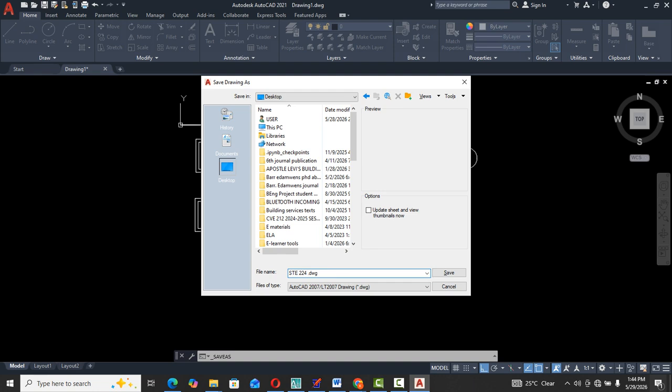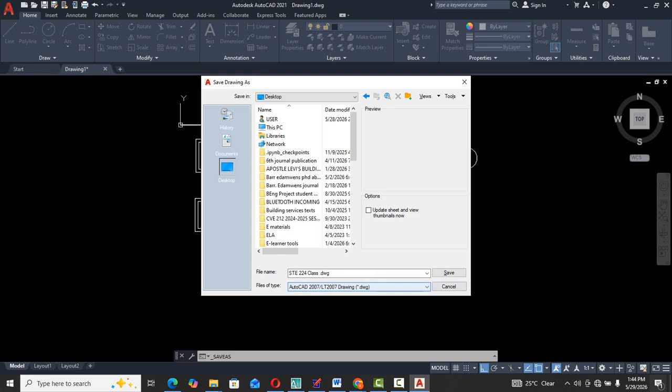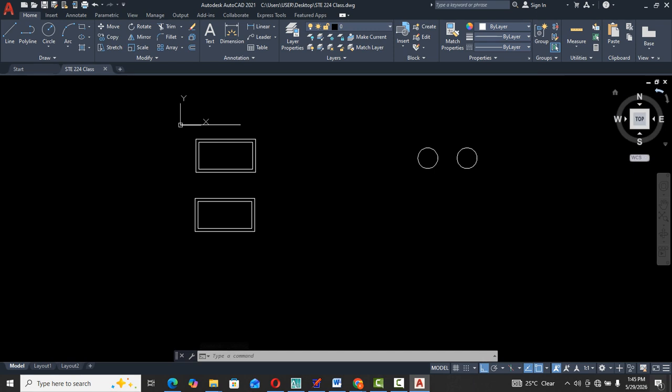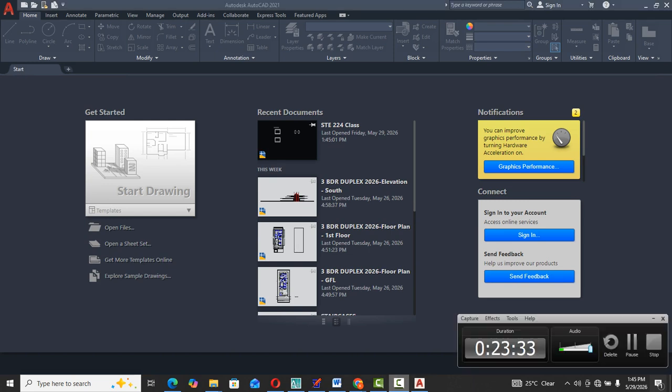If I uncheck it, it goes free. If I want it to be polar, so that it gives me angle and bearing, I can do the same. So if I select the orthogonal option, and I move, you see that there's a number, 42.7517. I can just put 3000 and type enter. I'll type enter again, so it escapes.